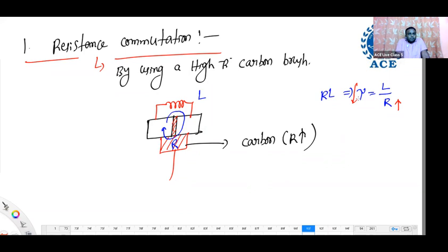Five time constants. If the time constant reduces, the value of five tau also reduces, which means you quickly get the output response. The signal reaches steady state very quickly if the time constant decreases.